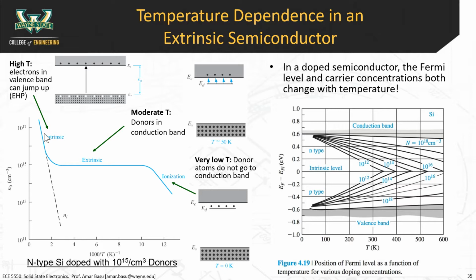So there are two types of scattering mechanisms that we talked about. One mechanism becomes significant at high temperatures. Another mechanism becomes significant at low temperatures. Impurity scattering becomes significant at low temperatures. Lattice scattering becomes significant at high temperatures. So silicon operates well at room temperature, but when we go from room temperature, just 25 C, up to 100 C, then we start to get these lattice scattering effects that become important. Lattice scattering decreases mobility.